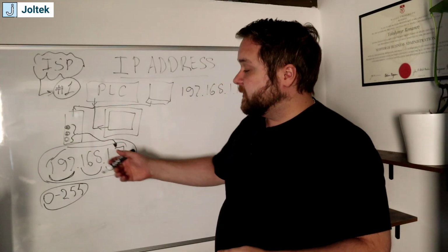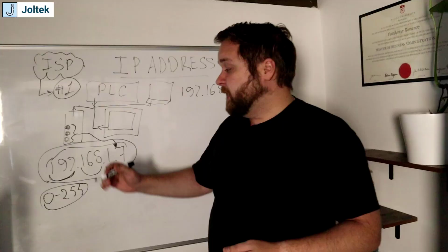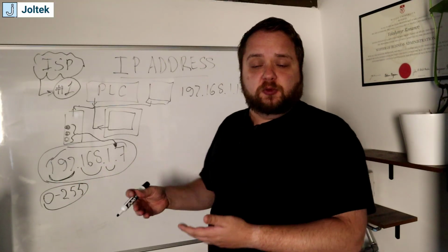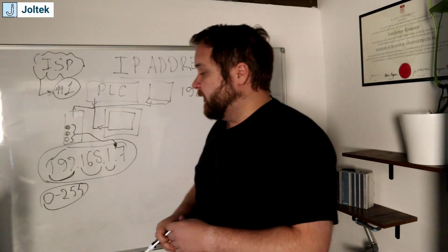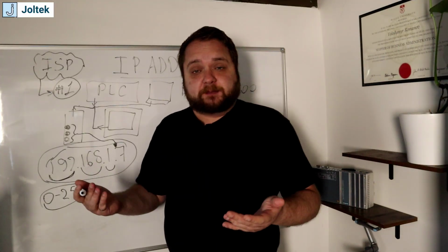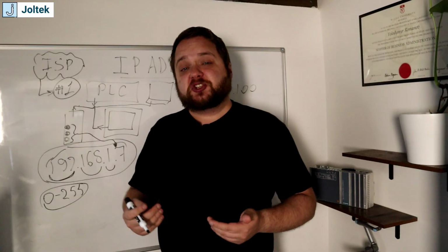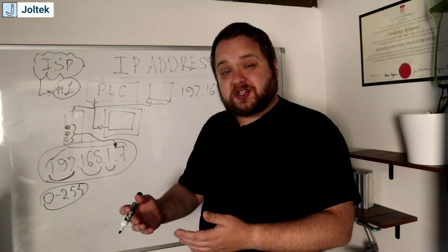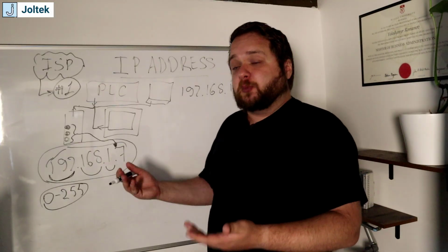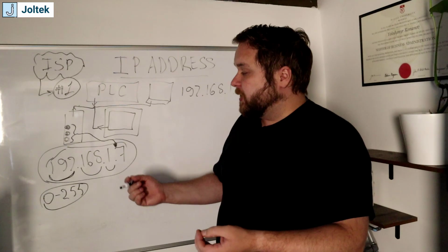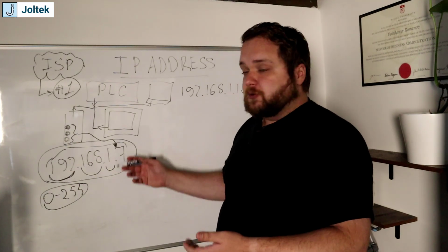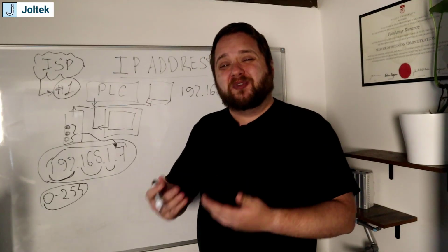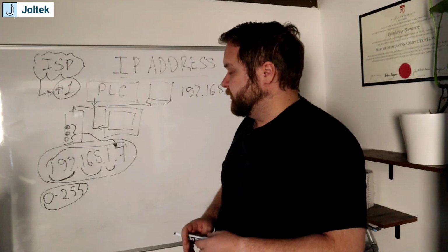So in that case, if you have a VFD with the dip switches, you can set it to 192.168.1. anything you'd like from 0 to 255. And why is that important? Well, because then you can take that into consideration and design machines and networks that will allow the technicians and engineers to easily swap out parts. And so basically what I'm trying to get at is that it is an easy to use scheme, at least in the world of Allen Bradley and other vendors that have provisioned hardware for the private networks.